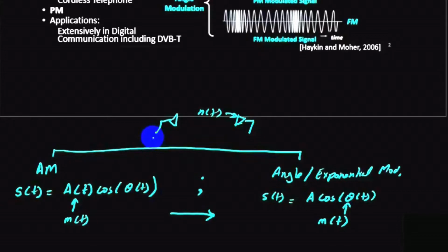So we will lose the information. But in angle modulation, the amplitude is not conveying any information. In fact, it's the phase which is conveying information. So small changes in the amplitude of the modulated signal would not have any influence on the received signal, and hence it will be more resilient. Therefore, we will lose on the bandwidth in FM, yet we gain on high-end quality reception and reliable data communication.